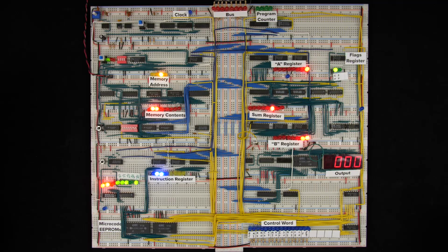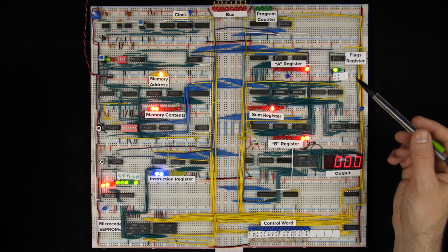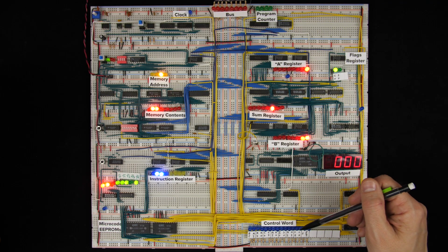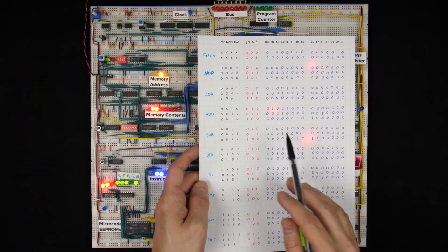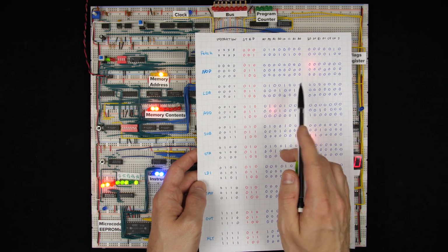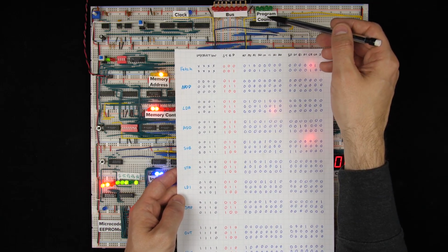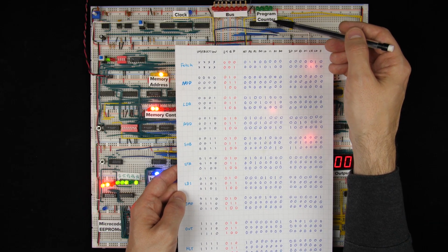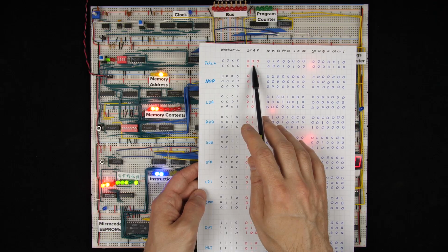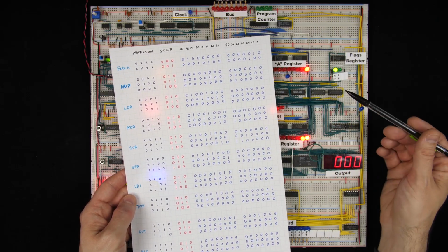Now that's an unconditional jump. It's always going to jump no matter what's going on with the flags register over here. But how can we build a conditional jump? Right now, the control word is the result of a lookup table that depends on the instruction that we're executing and what step of that instruction we're on. But since it's the control word here that controls whether the program counter is being updated or not, we need this control word to depend not just on the instruction and the step, but also on the condition, whether a particular flag is set in the flags register.